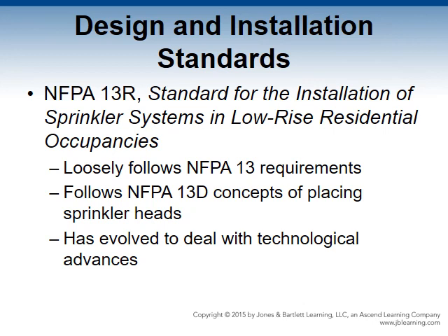It loosely follows NFPA 13 requirements, including the installation of at least one fire department connection in buildings over 2,000 square feet or more than 1 story. Sufficient water to support multiple sprinkler heads flowing simultaneously, as well as design provided by hydraulic calculation. Hydrostatic testing consistent with the NFPA 13 requirements is also in there. It follows NFPA 13D concepts on placing of sprinkler heads in areas where fires are most likely to start. The standard has evolved to deal with technological advances and other classifications to existing requirements.